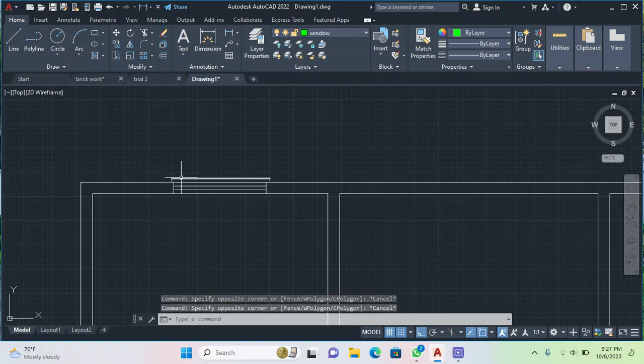So what we shall do, you place shift, you click that line, also click that line, and that line, then that line. As you're still placing shift, you also pick that line. When you hold shift it helps you click so many lines and points you want.